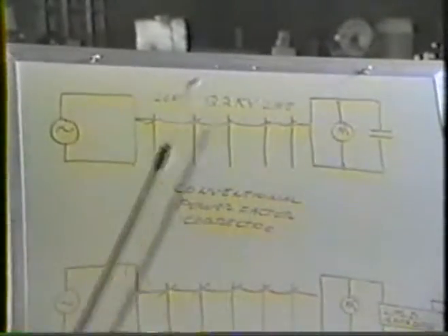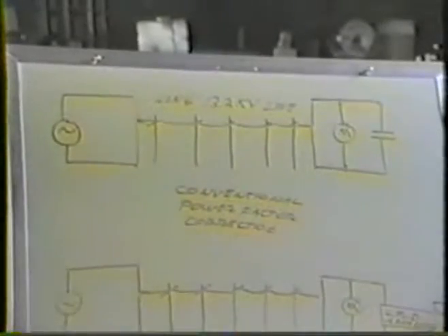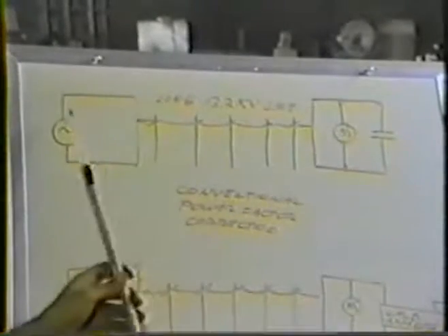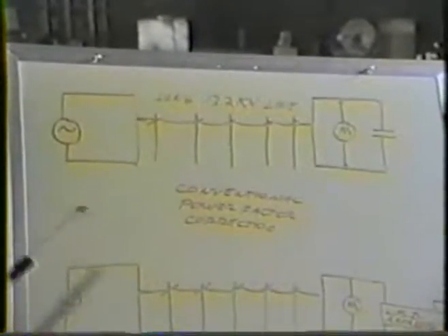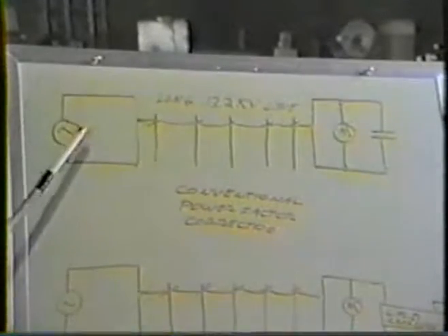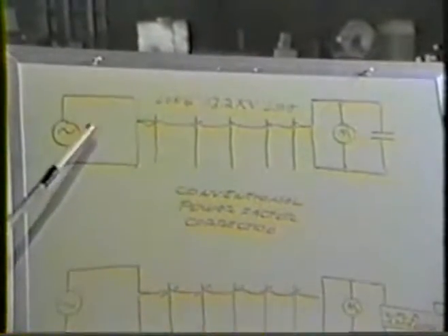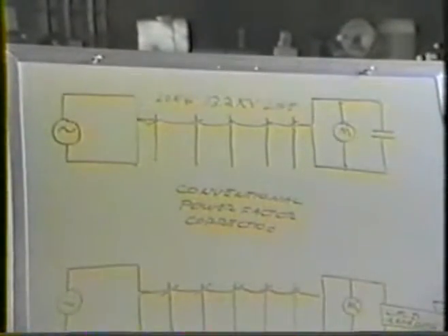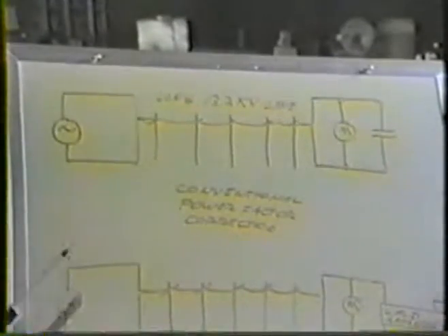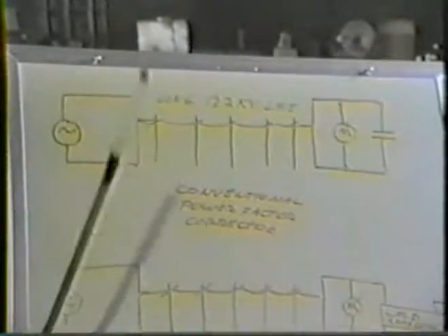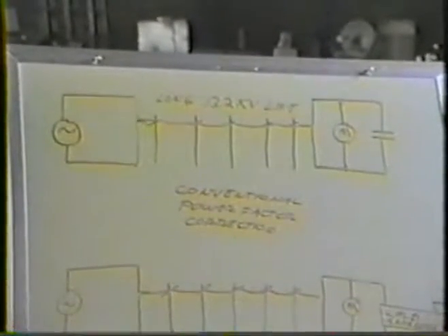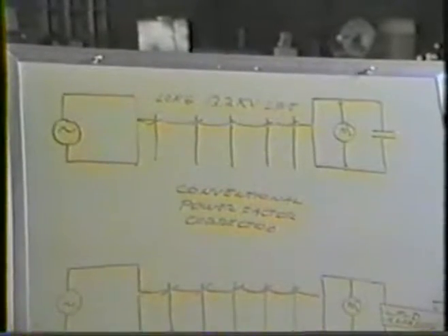The capacitor will resonate with this magnetic energy in the wire and cause the voltage of the system to raise as you go to the load, which of course is quite different than in normal DC circuits. So it's not uncommon in an alternating current power system that the voltage will start off nominal at the generator, which is usually 13.2 kV, and go up to 13.8 or 14, and if you remove the motor, it would go up to infinity. What happens when this is done, when the voltage gradient raises at the plant, the kilovolt ampere reactive hour meter will start to turn backwards, which usually causes trouble with the power company.